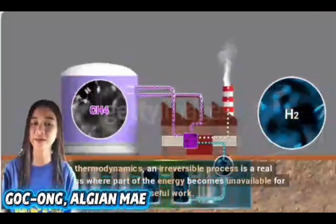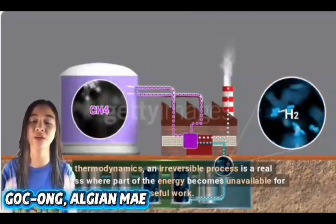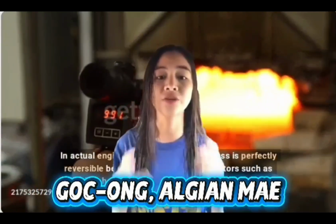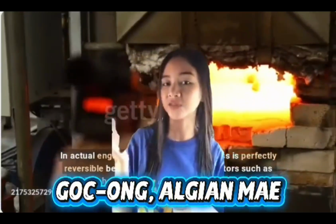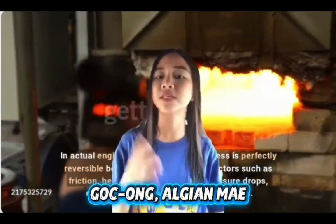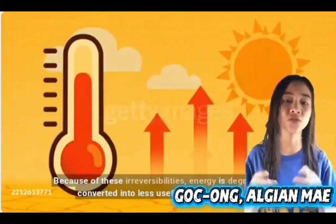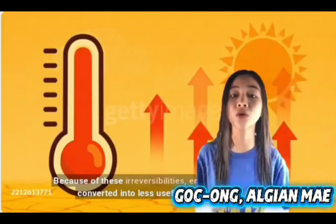In thermodynamics, an irreversible process is a real process where part of the energy becomes unavailable for useful work. In actual engineering systems, no process is perfectly reversible because there are always factors such as friction, heat transfer, turbulence, pressure drops, electrical resistance, and mixing of fluids. Because of these irreversibilities, energy is degraded and converted into a less useful form, usually heat. This results in what engineers call losses.